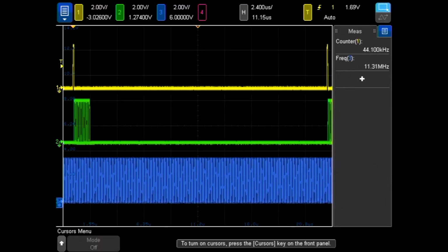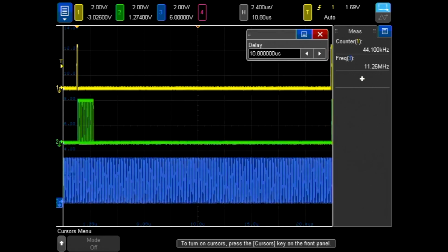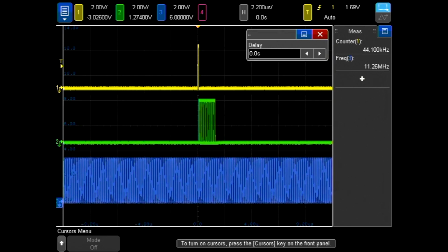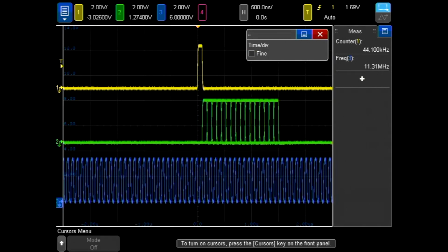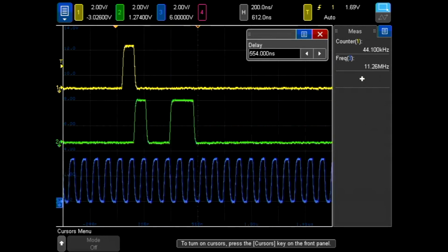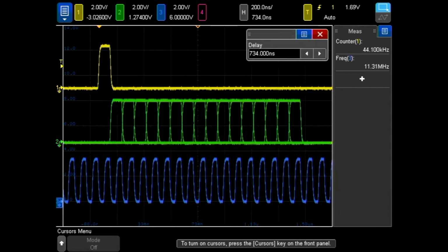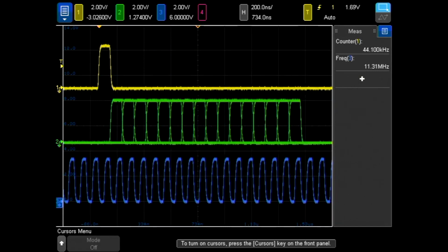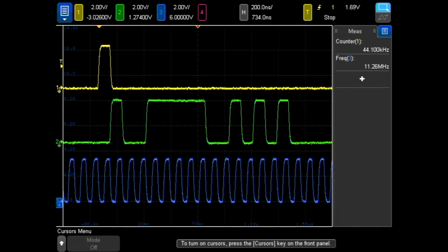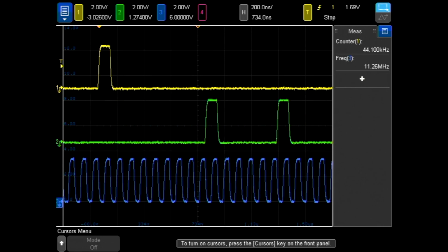They're all connected. And if we look at the oscilloscope picture, here it is. We can see green data has appeared, and I'm going to bring it to the center and zoom in on it, really zoom in a little faster. Those rapidly changing time slots are the bits. And if I hit the single sweep button, so the oscilloscope will do one capture at a time when I hit this button, there, that is the data.